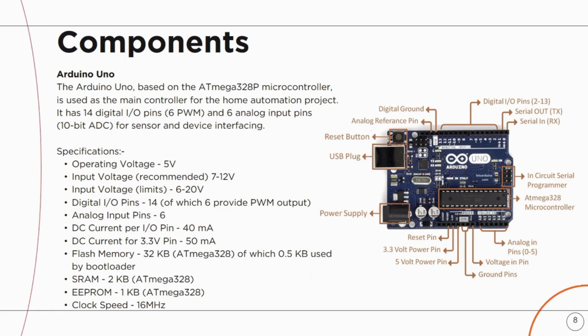The project made use of a few components. One of the main ones is the Arduino Uno. Arduino Uno is based on the ATmega328 microcontroller and is used as the main controller for this project. It has 14 digital input-output pins, out of which 6 are offering pulse width modulation.